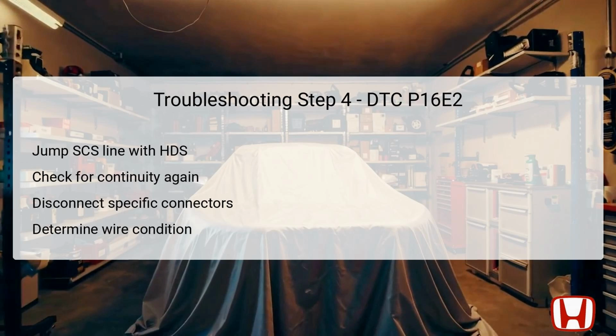While doing so, disconnect these specific connectors one at a time: the 12-volt battery sensor 3P connector and the PCM connector A, 51P. If the continuity ceases when one of these connectors is unplugged, it indicates that the LIN line or battery sensor wire is operational. Therefore, the issue likely lies in the component that caused the disconnection. If continuity remains, it suggests a short within the LIN wiring, which needs to be repaired to restore functionality. This step is critical in narrowing down the area of failure.